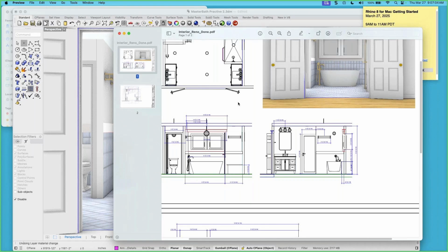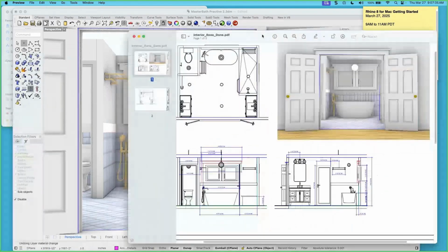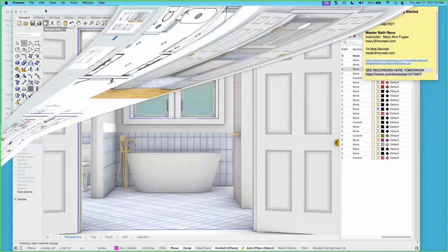So when we're designing for home construction, usually a 1/4 inch. I like to aim for 1/8 of an inch, but if I add any more precision to that, my contractor isn't going to follow it anyway. So we just want to be in the ballpark, and 1/8 of an inch is a real good place to aim for. So you have that in the set that you will download.